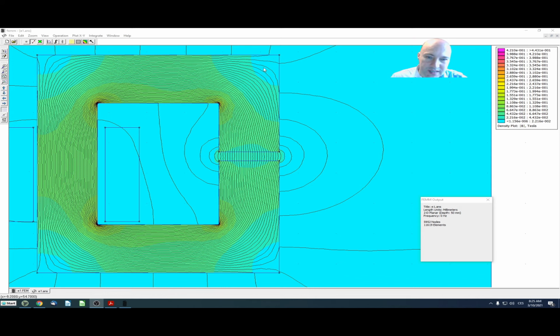This means that here we basically do not need that material, because all the magnetic flux is flowing basically here, like that, and here the flux density is much smaller. So we could also optimize the design in terms of mechanics, so that, for example, here we round the edges and make it lightweight, and we don't need that much material.